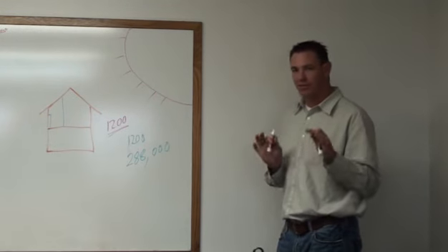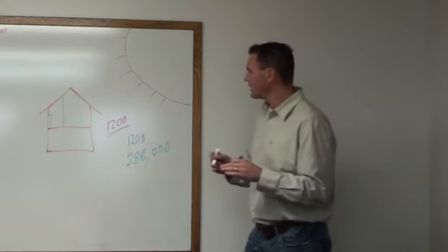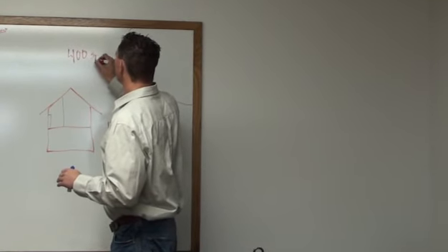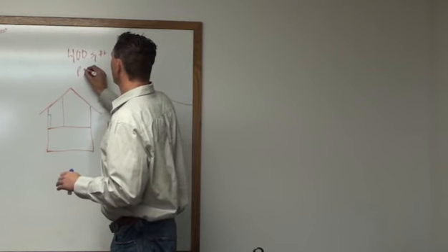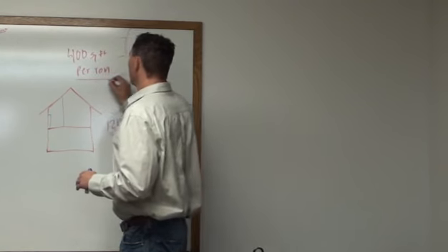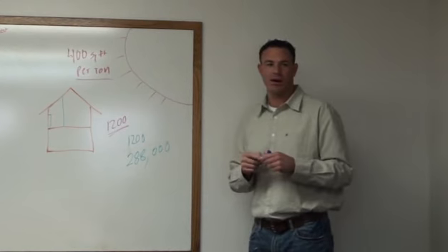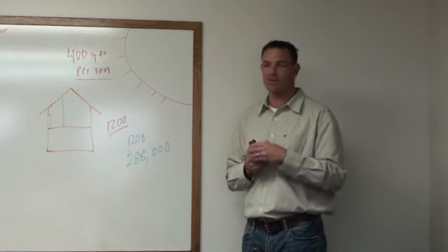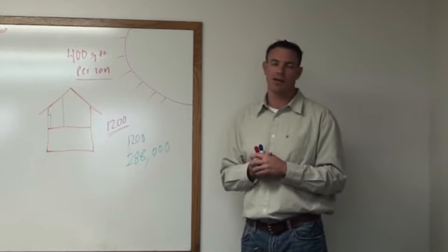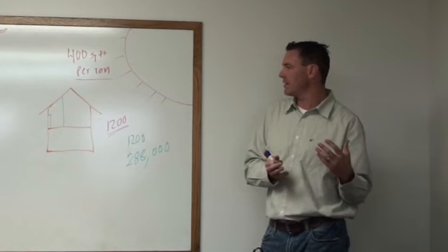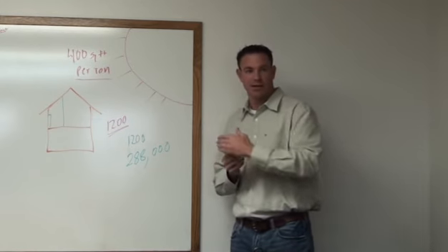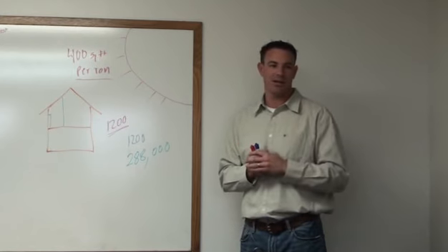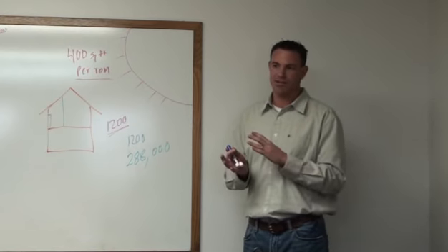Just to give you guys a general rule of thumb, an industry standard, is about 400 square foot per ton, okay? Now that'll vary depending on altitude. Altitude is a huge factor when you're talking about airflow, and I told you guys the airflow is extremely important. If you've got a unit that's in, say, Missouri, Missouri's going to have a huge amount of condensate in the air, or humidity, relative humidity. So there's factors to think about there.